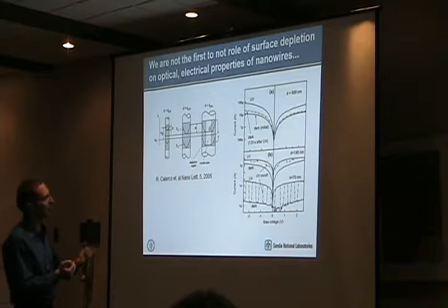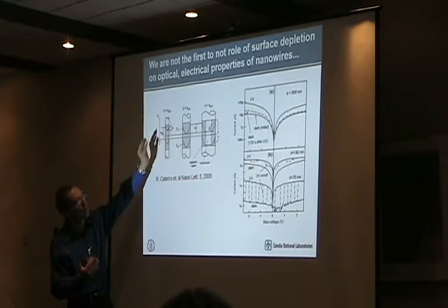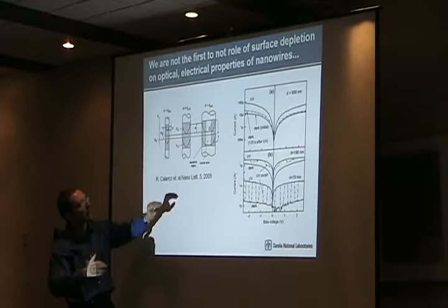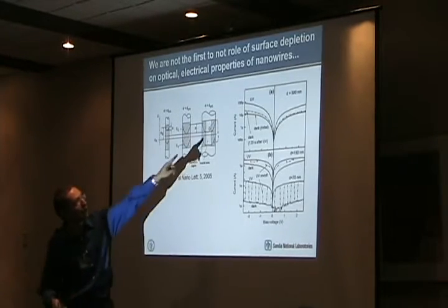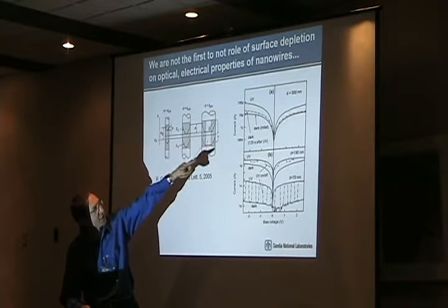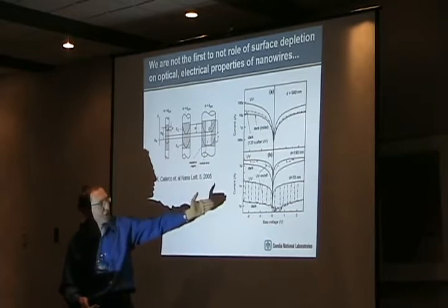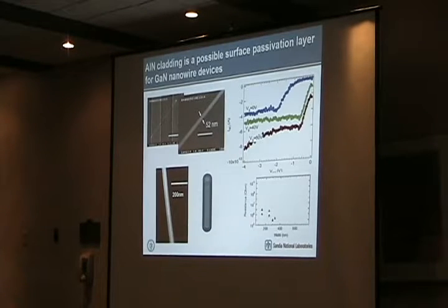You can understand that if it's very small, and there's surface state, there's always going to be a bending. But if it's very wide, then the carriers are going to be separated, so it takes a long time to recombine, the response is very slow, and they're very conducting. When the diameter is small, they're very resistive, but they're very fast. That is actually a useful thing.